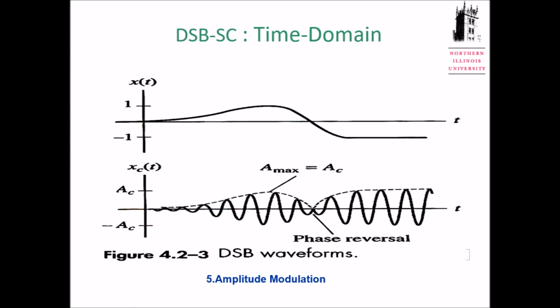Okay, so this time when we plot the time domain picture, there is a huge difference. Now I do not have a large carrier. So this is my original time domain signal, and this one is modulated. We can find my envelope is similar if my signal is positive. However, when my signal is negative, it's flat.